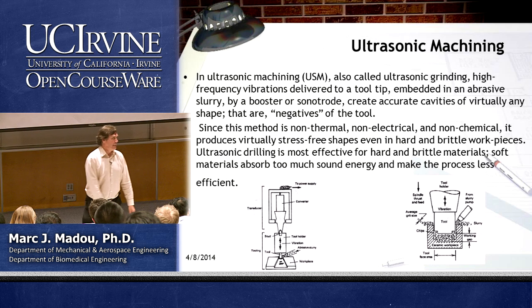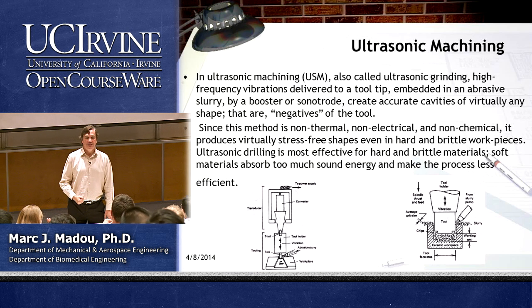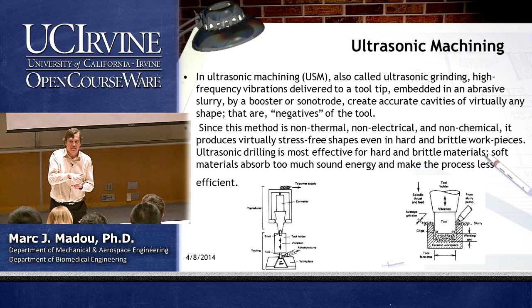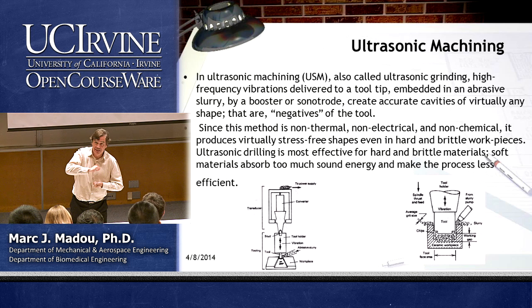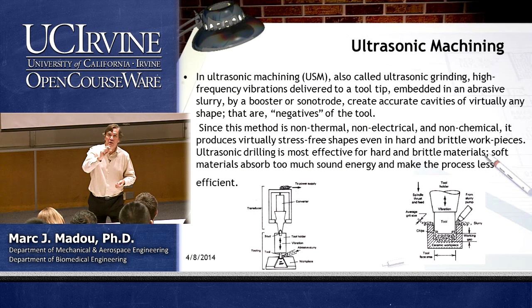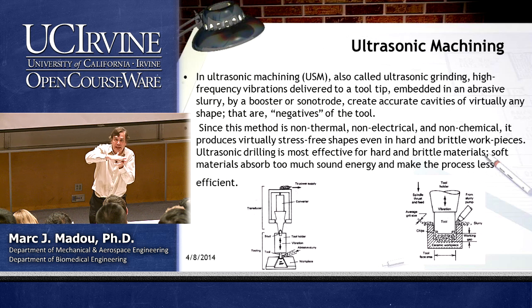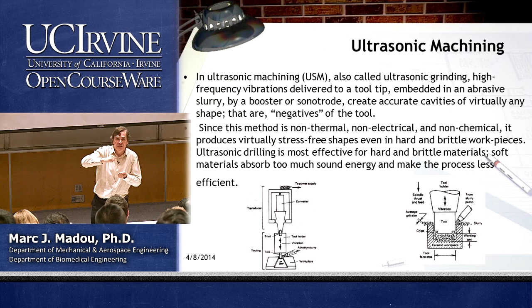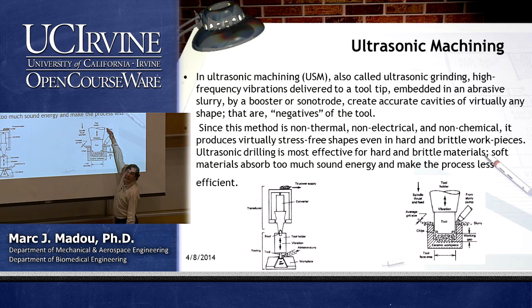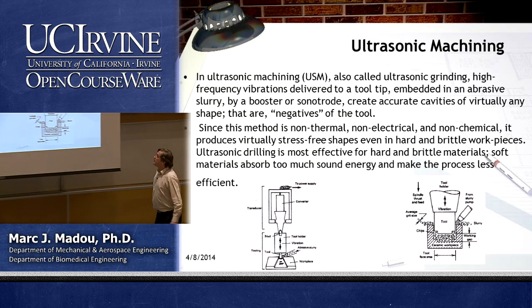So piezoelectricity, remember that? So piezo is from the Greek, pressure, right? So if you have certain crystals, let's say quartz, and you pressurize the quartz, you will have electricity. And vice versa, if you put an AC signal on a quartz crystal, the quartz will expand, contract, expand, contract. That's what happens. And so it's that expansion and contraction of the crystal stack up there that makes this go up and down. But so let's read through it together.